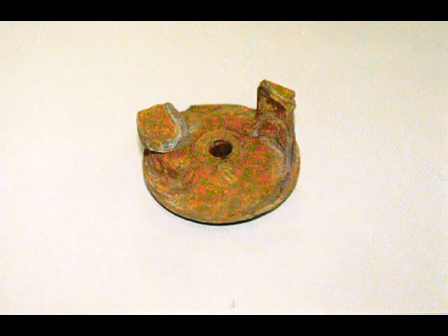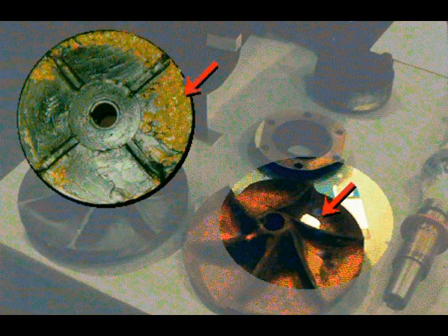Pockets of low pressure can be created by the action of the vane tips or outer edges of the impeller. This can be corrected by increasing the casing pressure or lowering the speed of the impeller. In addition to pitting of the impeller, noise and vibration will be generated. The noise will resemble that of a bowl of rocks being shaken. If cavitation is not corrected or prevented, there can be serious mechanical damage to the pump.